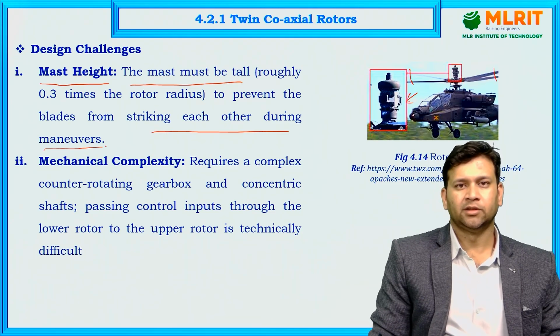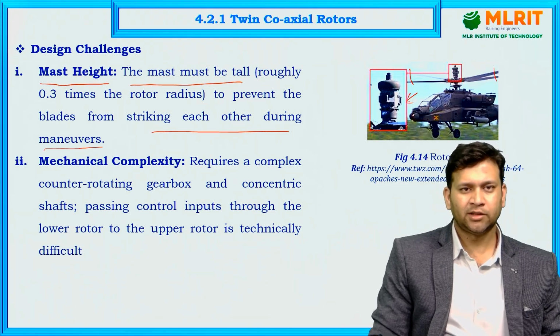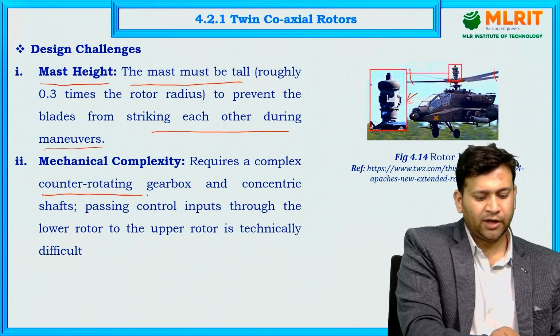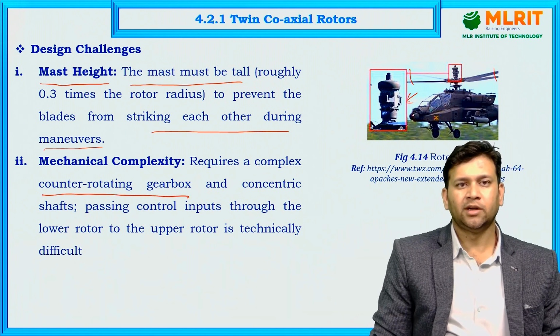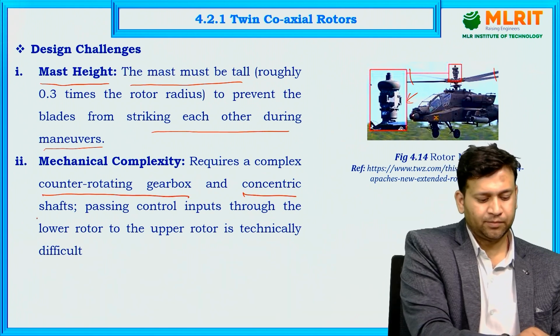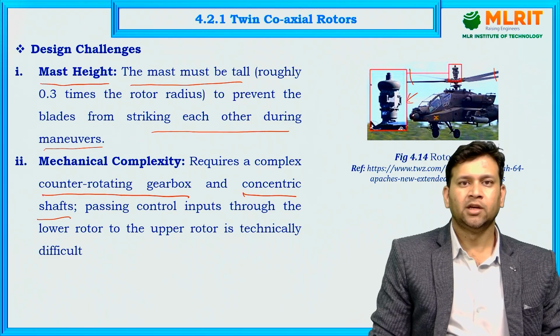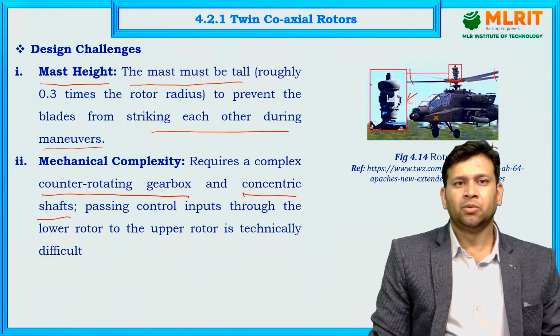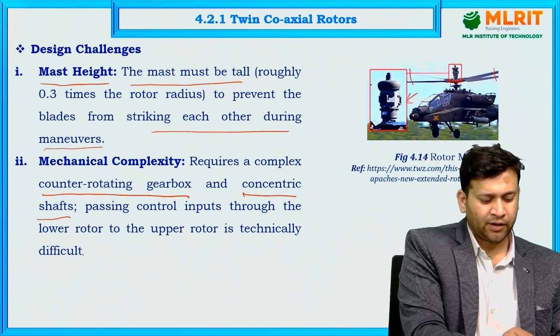Mechanical complexity. It requires a complex counter-rotating gearbox and concentric shafts, passing control inputs through the lower rotor to the upper rotor, which is technically difficult.